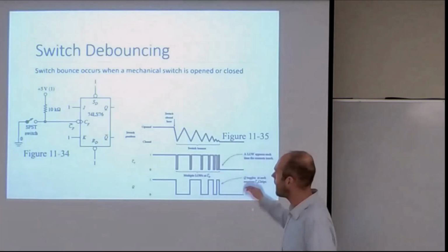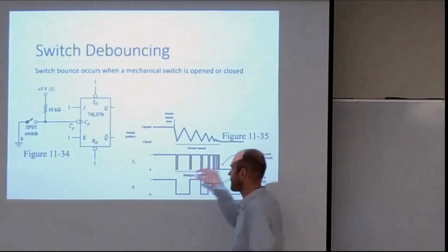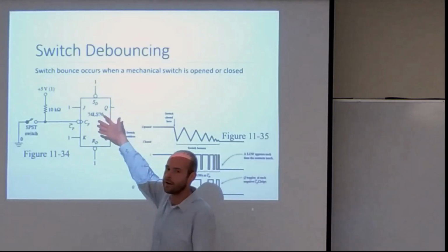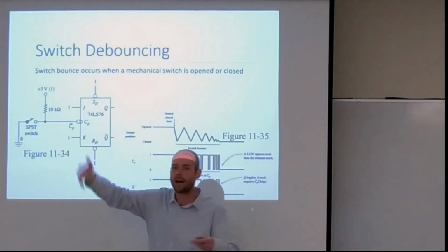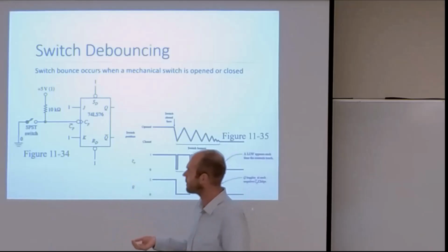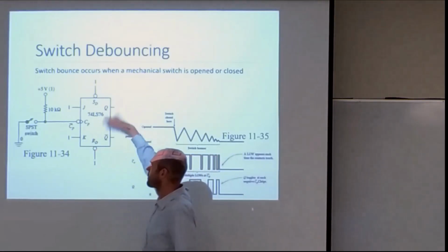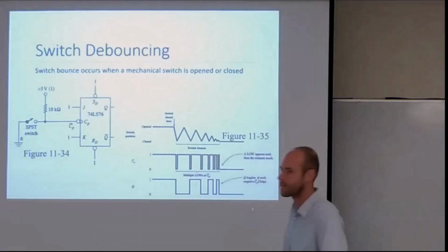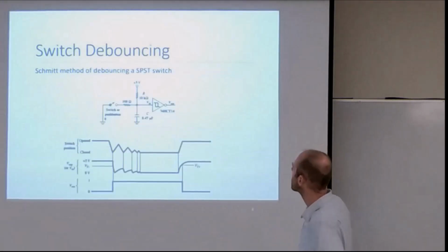This first figure here is just illustrating switch bounce. And if you had a bouncing switch on a toggling flip-flop, like say you were counting, like we saw in our previous labs, we had to debounce in ICE Studio. Otherwise, this count would go up multiple times. However many bounces would be how many numbers it toggled or incremented.